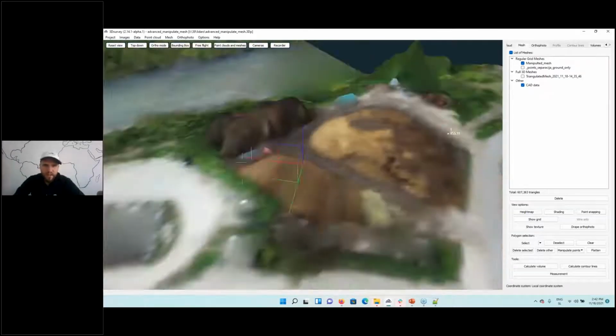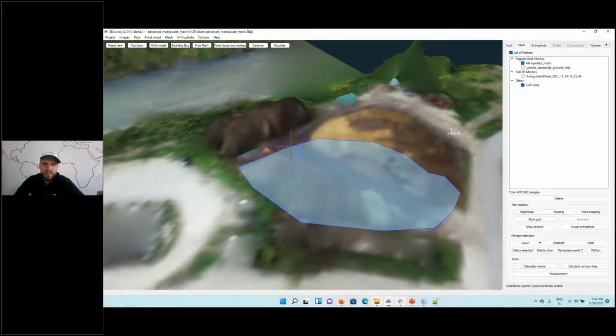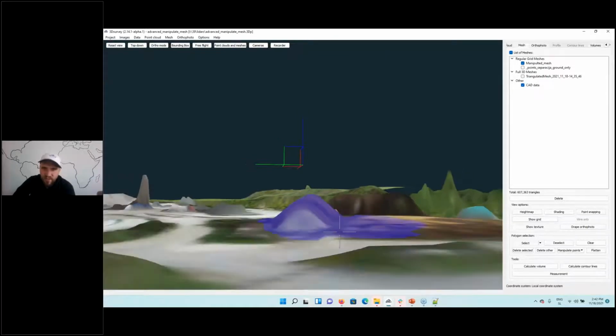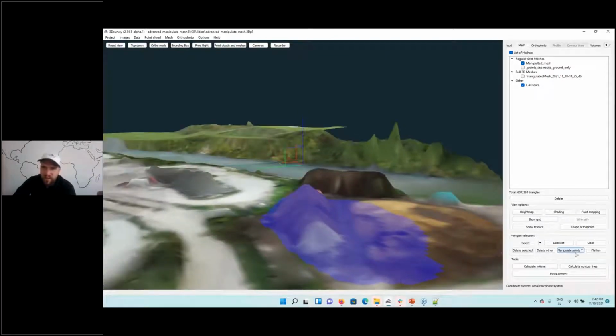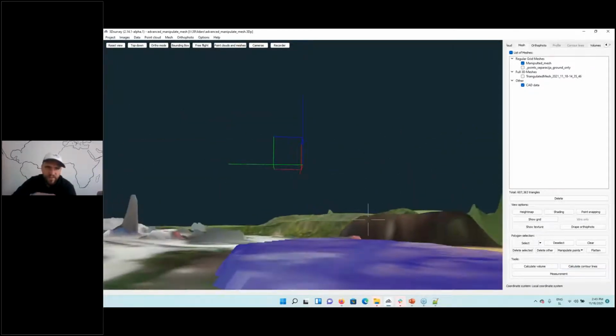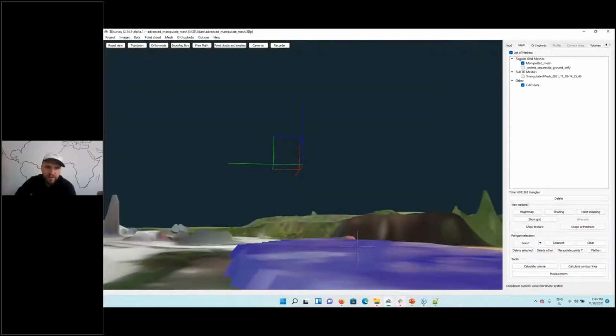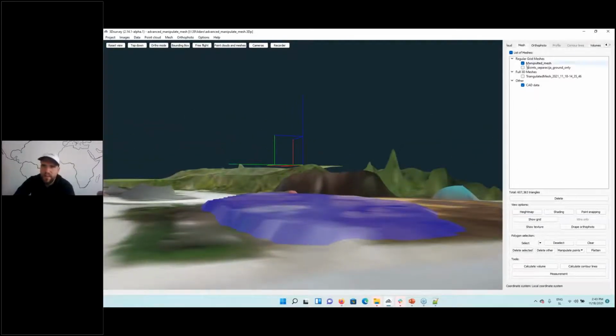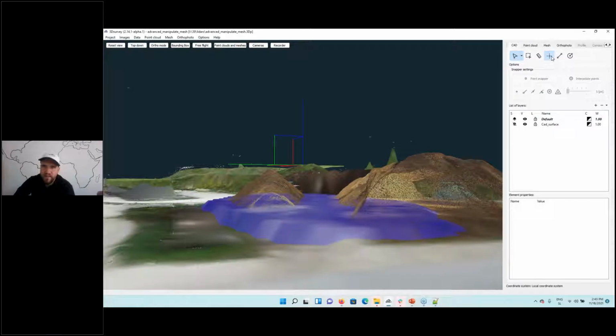We want to make it flat. So we can say if this is our area of interest, and we take a steamroller and we make this area flat. We don't want to add or remove any material from the site, what height of the terrain will we get? So there is a function here under manipulate points. It is under average height. If we press this one, we get average terrain height. So that means if we flatten an area, we move the terrain so that it's flat. This will then be the height that we will get.